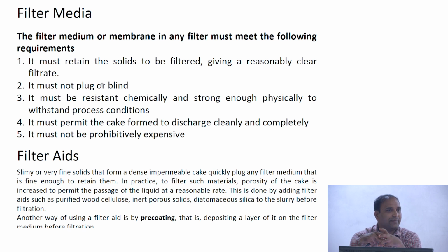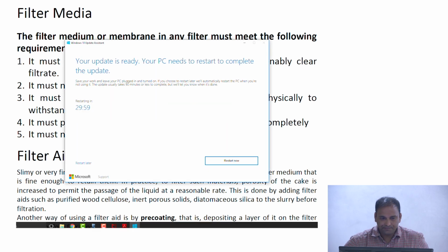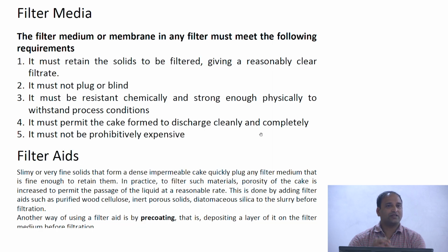What this basically means is that I have a filter medium, and with time, depending upon the operation that you're dealing with, these solid particles may get embedded in the filter medium. Of course, that depends on several factors: the type of particle that you're working with, the pressure difference, and things like that. The moment you have solid particles incorporated into the filter medium, that's called plugging or blinding of the medium. And of course, that should not happen.